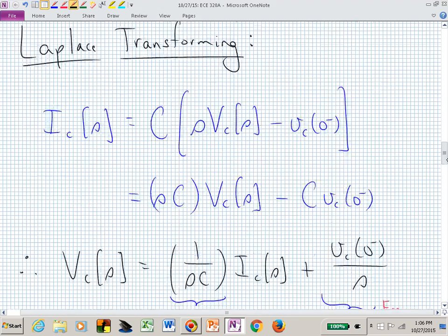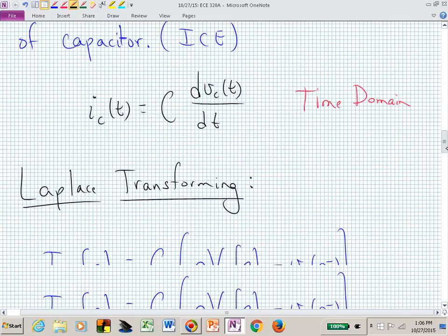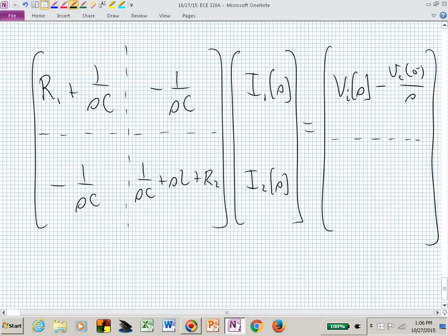If we have the same thought process for I sub 2, how do those sources enter into the second row of my right-hand side? Both negative signs, both positive, one or the other. Does the capacitor initial condition source enhance, or they're both enhancing I2? If I increased both of those sources individually, they would both increase I2. They are going to come in with a positive sign.